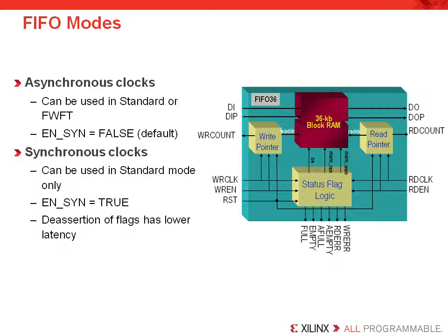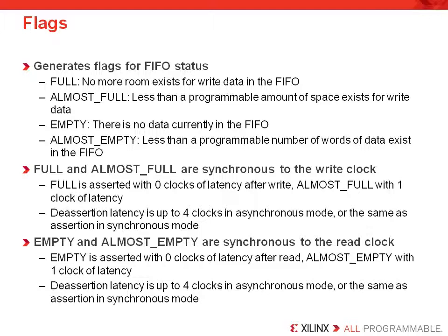The FIFO core also can generate numerous flags which are selectable by the user when you use the core generator GUI. Likewise, these flags do not require any additional logic, but there's support for a number of different FIFO status flags, including the full, the almost full, the empty, and the almost empty flags, which are pretty standard operation for any FIFO a designer may have built. There's also support for full and almost full flags, which are synchronous to the write clock, and also the empty and almost empty signals, which are synchronous to the read clock.